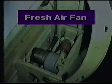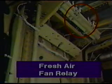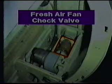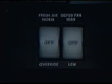The fresh air fan system includes a fresh air fan unit, generally called the fresh air fan, a fresh air fan relay, and within this duct, a fresh air fan check valve. Electrical control components include the switch in the cockpit and one of the nose gear position switches, which is also part of the circuit.